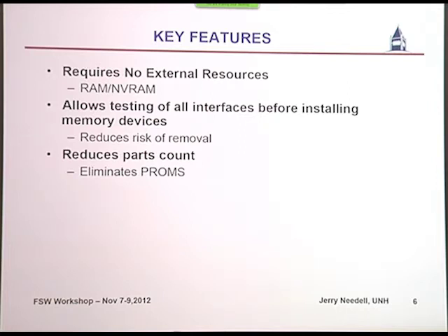This also eliminates really the need for a PROM. We really don't need that separate step, because that highly reliable, non-reprogrammable device is now built into the FPGA. So it reduces the parts count and makes the board simpler.